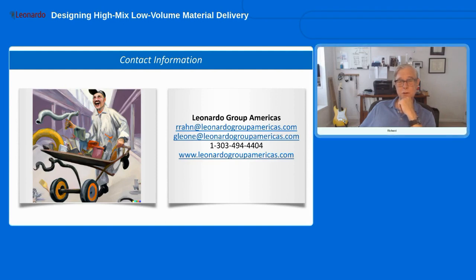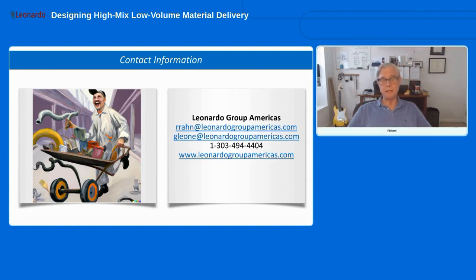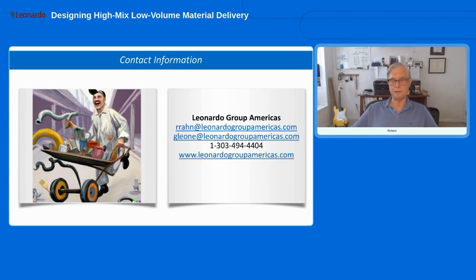directly to the supermarket, then one of the requirements is those suppliers have to be certified, and part of the certification is they need to deliver 100% quality. And what Toyota does, by the way, is when they have a new supplier, or not just a new supplier, when they have a new item, a new part, they will do a 100% inspection of the first, I think it's the first 3 deliveries from that supplier. And if there are no problems, then they will allow that kind of direct delivery to the supermarket. Otherwise, there have to be some corrective actions taken. So it's not that they take their word for it that it's high quality. They actually will check the first 3.